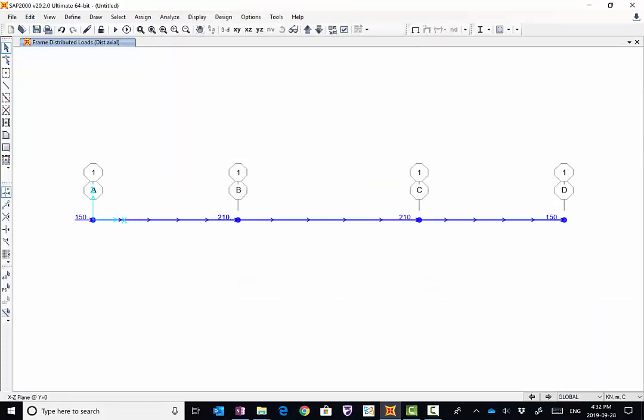So far we did apply the load, but we have a challenge now. The element that we are using is a frame element, and so far your structure is unstable because we didn't apply any kind of boundary conditions. I need your full attention here to understand how we're going to reduce the degrees of freedom of this element from a 3D frame element to a unidimensional bar element, where you are expecting only 1 degree of freedom per node.